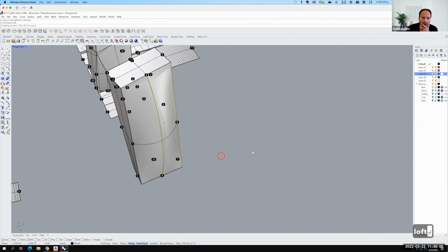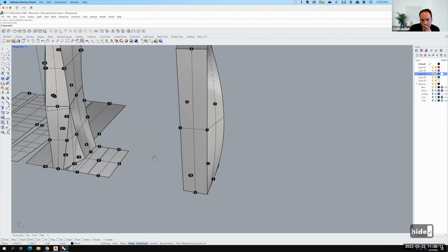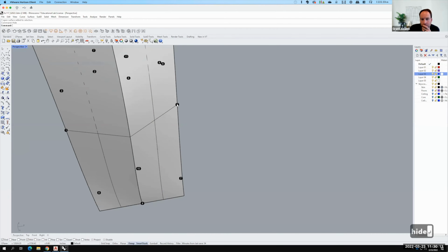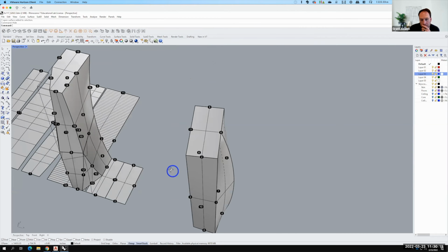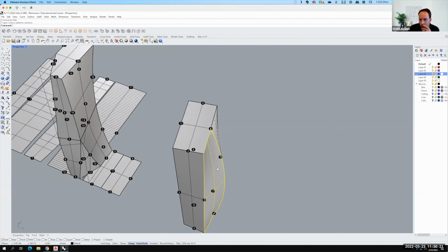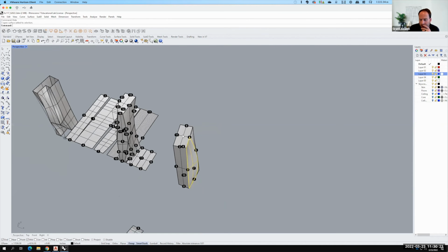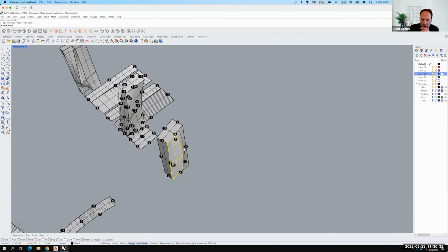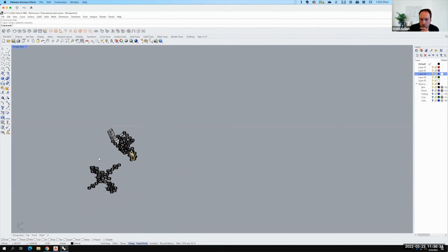And say okay, now if I hide the original surface, you can see that my adaptation still has a curve, but we've eliminated the second dimension of curvature. It's just a straight line there and there. So this would be developable and unrollable in the same way. If your building ends up having curvature in two directions, you may have to rebuild it. You may have to recreate it and make sure that you loft it around to get this end result.